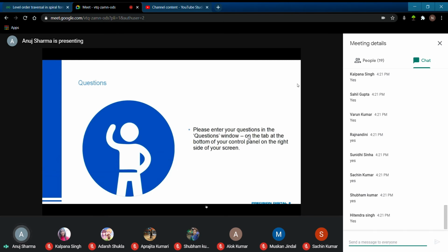This is from Chris. Chris says, correct me if I'm wrong, but passive loop means you provide the 24-volt power supply, and active loop means the 24-volt power supply is built in. You are absolutely correct. The general terminology is that if I have a passive loop output, then I have all of that current control circuitry, but I don't have any voltage power supply built in. So I can regulate a current if you give it voltage, but that's it.